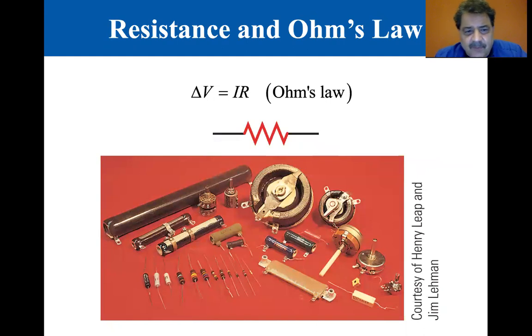Okay, here's a bunch of different resistors. You already were exposed to some that are on the bottom here. They have color bands. The color bands tell you what the values are. If you look at these round tubes, this brown round tube, that's a fixed resistor. But just below it, these other brown tubes, you can see that part of the wiring is exposed. Those are variable resistors. And you're going to be playing with a variable resistor when we do Ohm's Law. These that are round, where you can see the wire around it, also are variable resistors, and any of these that have knobs are variable resistors. The others are all pretty much fixed.